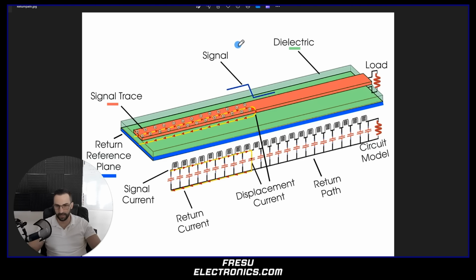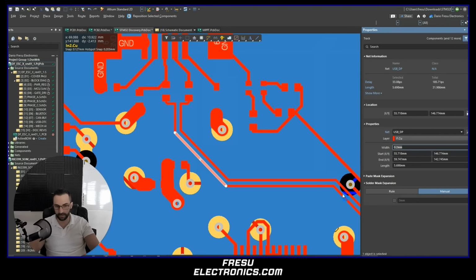So what happens when the impedance changes? The impedance is the ratio between the signal and the current at any point in time. So this means that if the ratio between the signal and the current changes, the impedance changes. But the same applies the other way around: if the signal is fixed but the impedance changes, then the current changes. Or if the current is fixed and the impedance changes, then the signal changes. You can see that this will create issues for us, because we want to have the signal as clean as possible. That's why we call it signal integrity: the signal has to be kept as clean as we possibly can, from source to destination. So not choosing an impedance, and not keeping it throughout the whole length of the trace, will cause mismatches between the impedances, and this will create reflection of the signal.